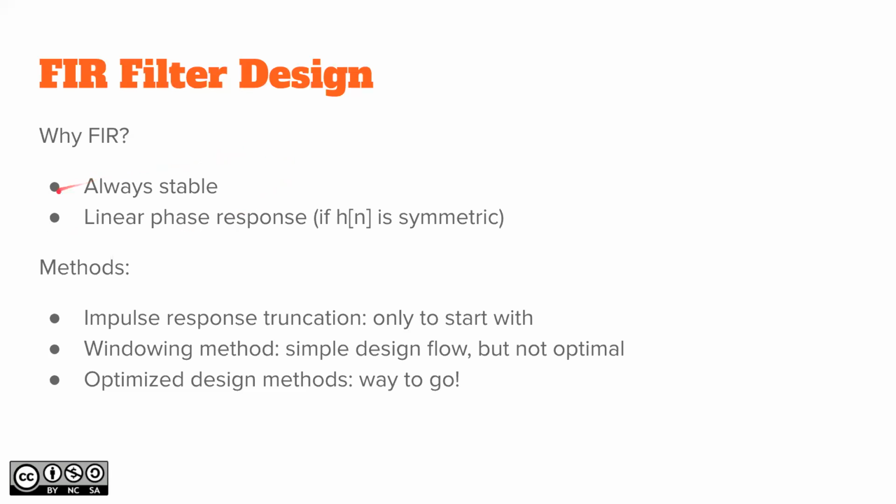But anyways, the easy part is it's always stable. You have only the impulse response as the parameters, and basically the linear phase response comes if h of n is symmetric, either positive or negative symmetry.